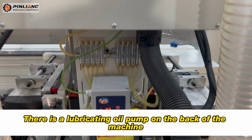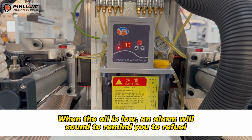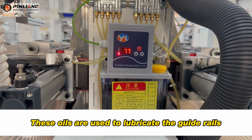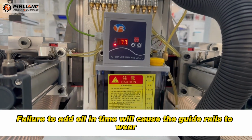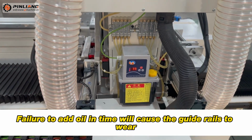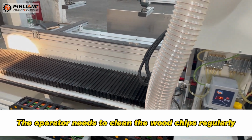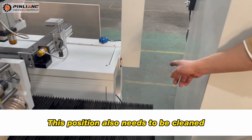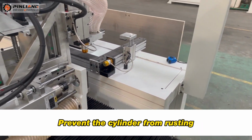There is a lubricating oil pump on the back of the machine. When the oil is low, an alarm will sound to remind you to refuel. These oils are used to lubricate the guide rails. Failure to add oil in time will cause the guide rails to wear. The operator needs to clean the wood chips regularly. This position also needs to be cleaned to prevent the cylinder from rusting.